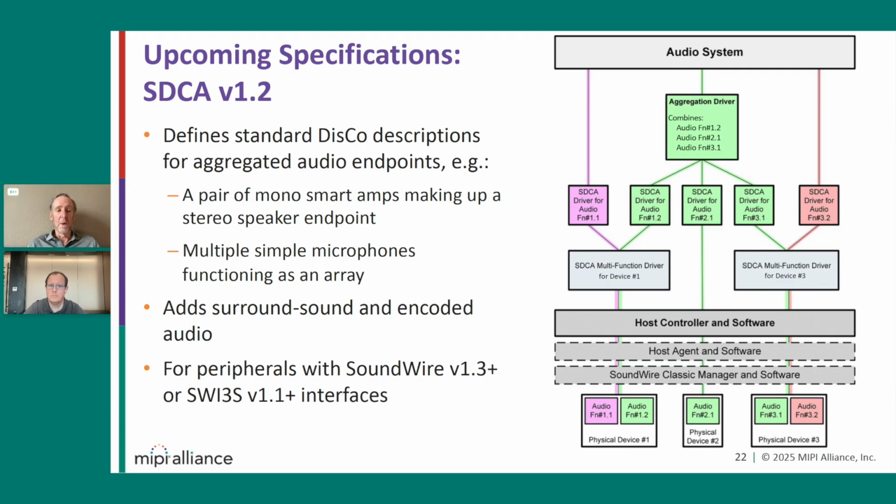Additionally, we're building in better support for interfaces like SPDIF and encoded content, so that the class drivers can now understand something more than just PCM audio. It can support encoded content like AC3 or other Dolby interfaces.